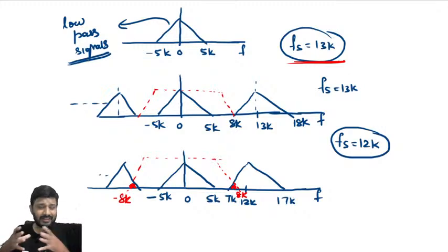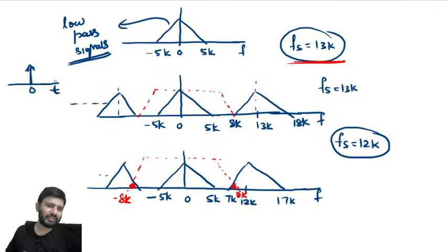And this is nothing but the sampling technique. What we have seen is ideal sampling, or theoretical form of sampling, where we multiply the signal with an impulse train. We will study in the first basic units that an impulse signal cannot exist in practice. If an impulse signal cannot exist in practice, there is no question of an impulse train. So the method we have seen is the ideal or theoretical form of sampling.